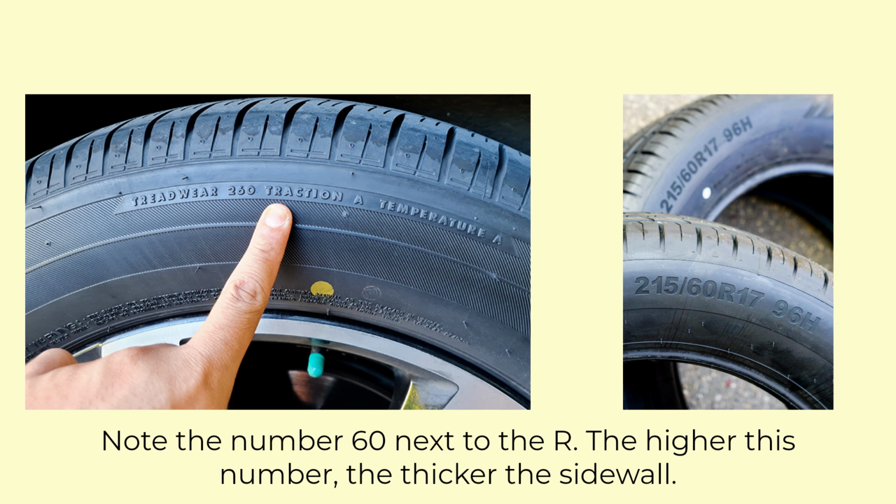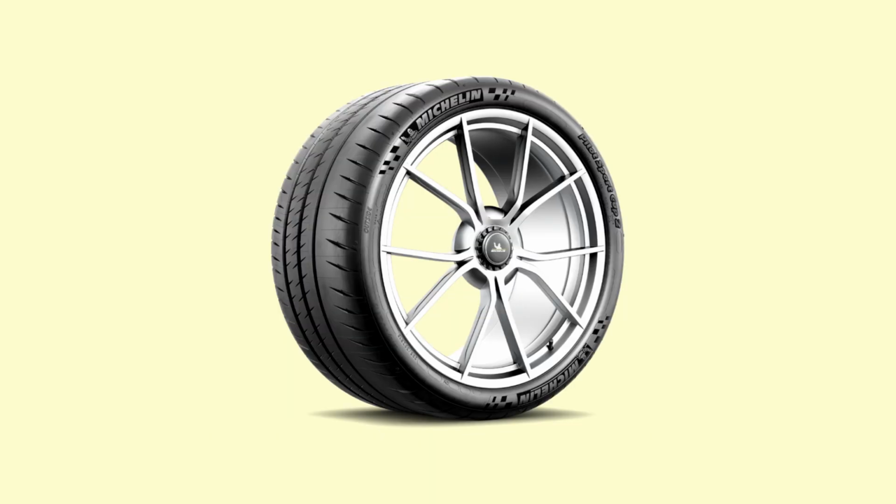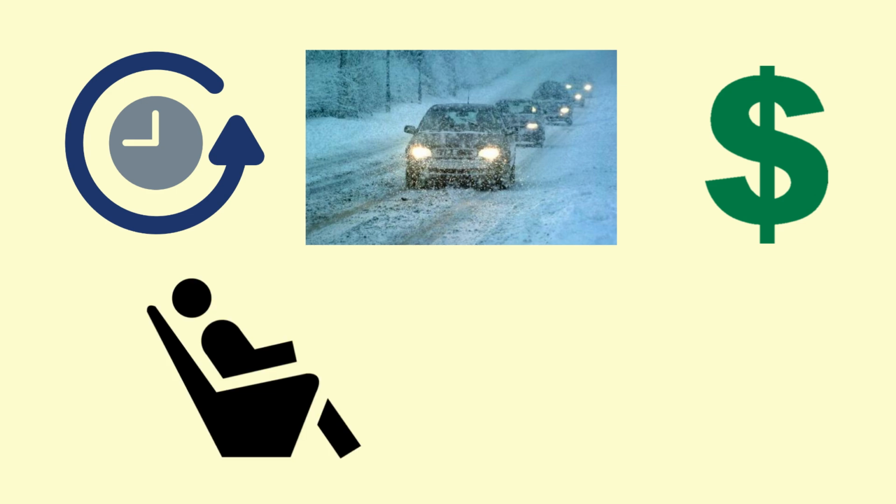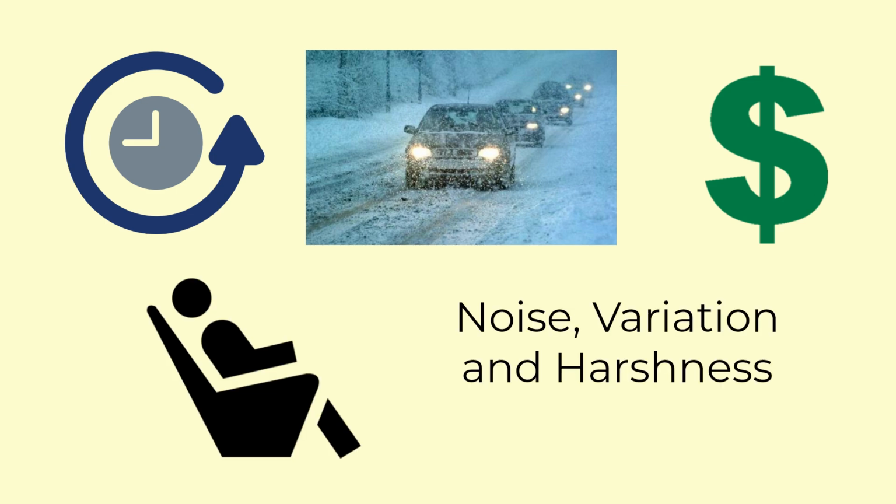The solution here is going with performance tyres, and whilst they have drawbacks in things such as longevity, inclement traction, cost, ride comfort, and NVH, there is inevitably increased grip to be had here, especially from the front end, which is inherently robbed of grip during initial turn-in.